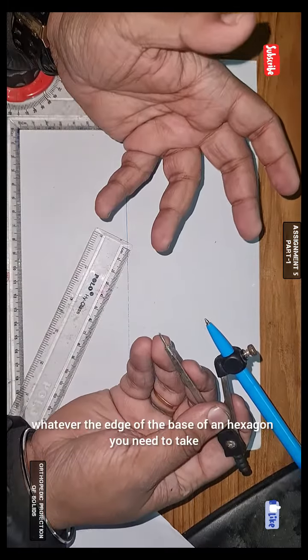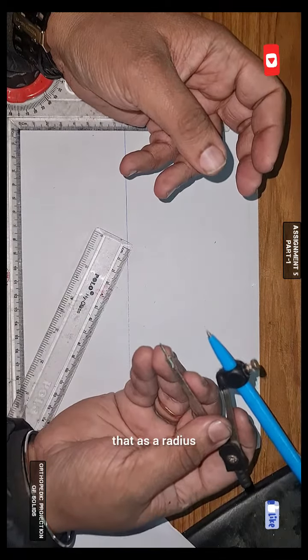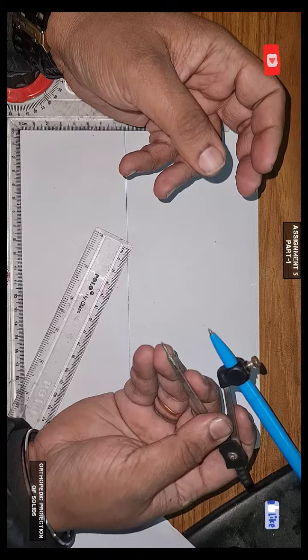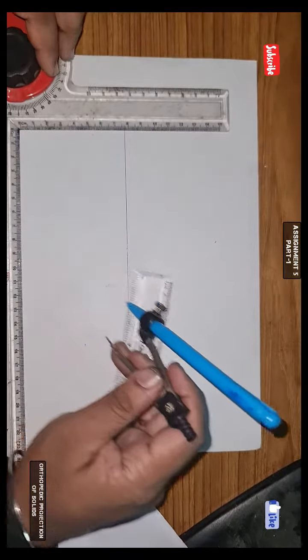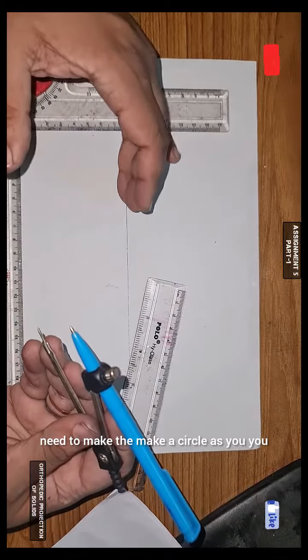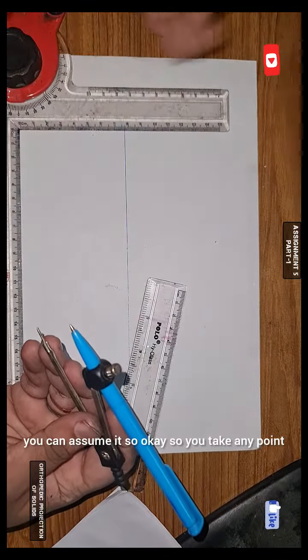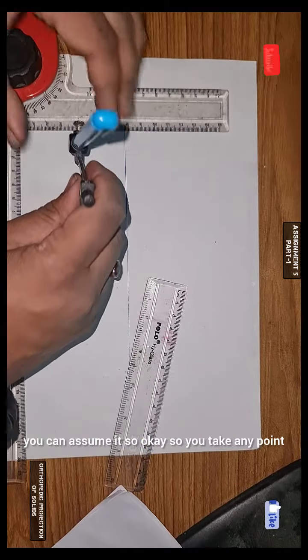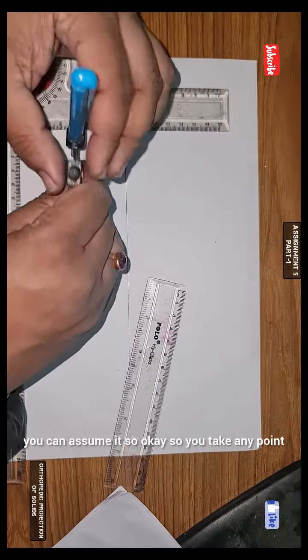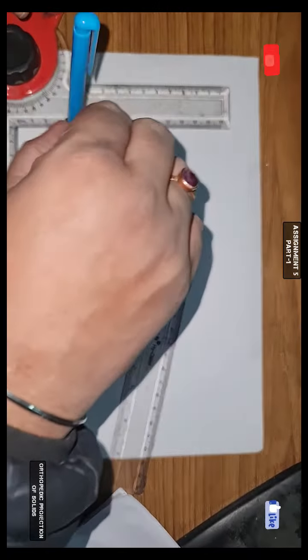Whatever the edge of the base of a hexagon, you need to take that as a radius. So you need to make a circle. As the distance from the XY line is not given, you can assume it. So okay, you take any point and make this circle.